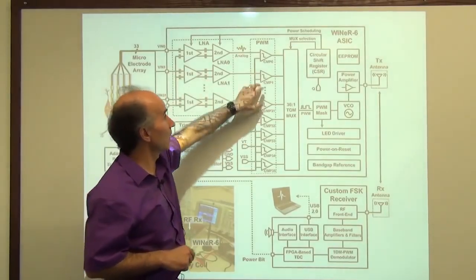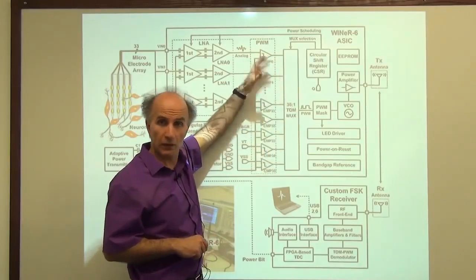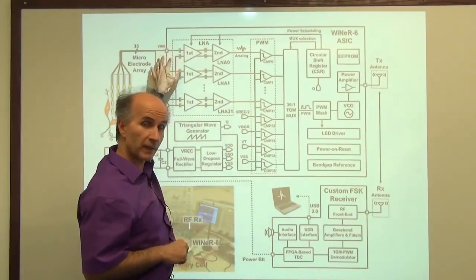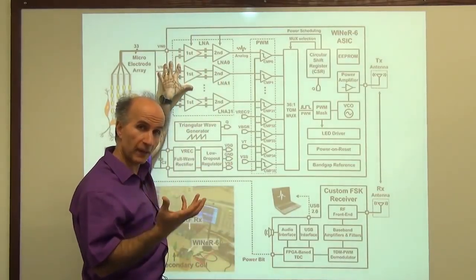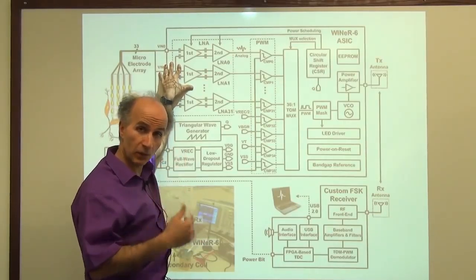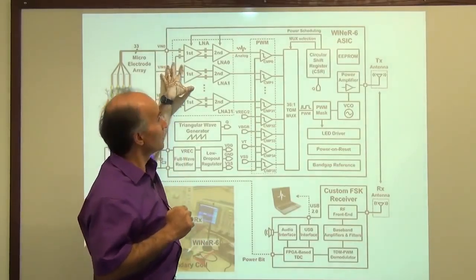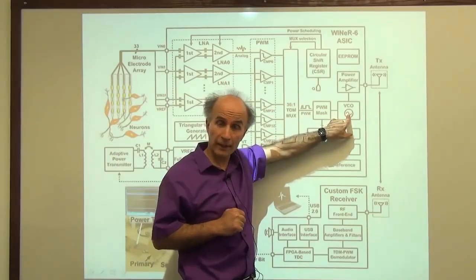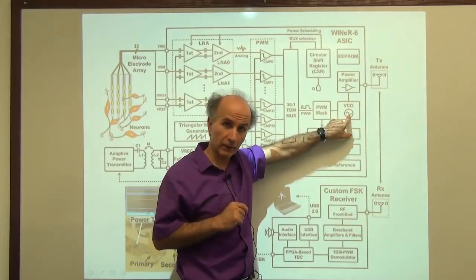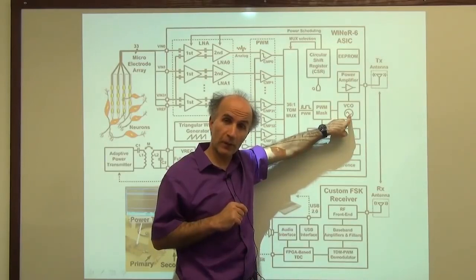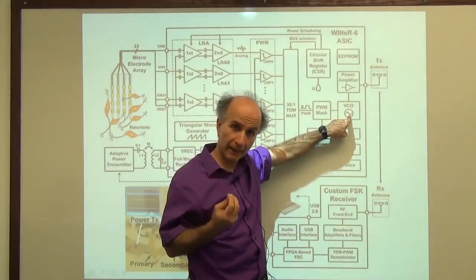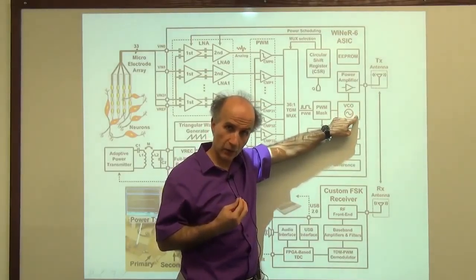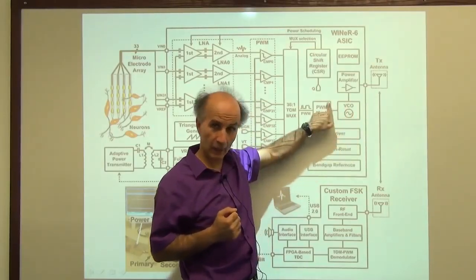Then we go to something else. This is called pulse width modulation. This is to process the data and eventually convert it to digital data. We would like to go from these analog waveforms to some digital representation that's easier to process, store, transmit, etc. So then that goes through here and it reaches an oscillator, a voltage controlled oscillator. Now this should be familiar. Remember in the Bluetooth example, we wanted to transmit data. What we did was apply the data to the control of an oscillator so that its frequency is modulated. And that's exactly what we do here.